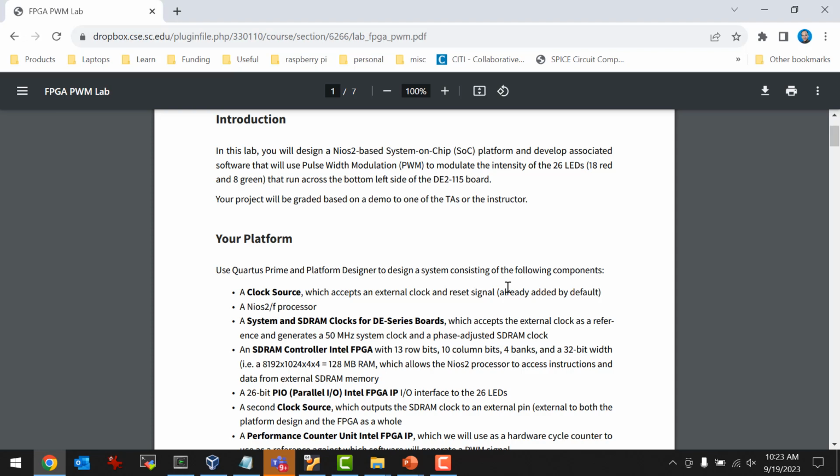Because if you get an Arduino, even the lowest end Arduino, the Atmel 328P, it's got hardware PWM in it. So why in the world does Intel not understand that we need PWM? Unclear. So that's a problem. In Lab 2, we're going to solve that by using bit banging, and then we're going to develop a hardware PWM in Lab 3.